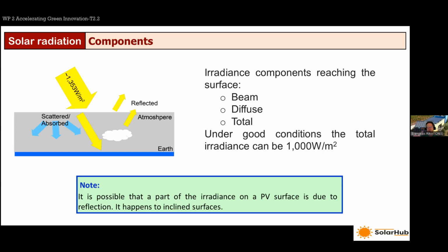Well, the testing of PV modules should always lead to data that are normalized. We always transform the measurements we do to standard test conditions, right? So in the end, you can measure either within a solar simulator or outside under real conditions, because we can also do that.